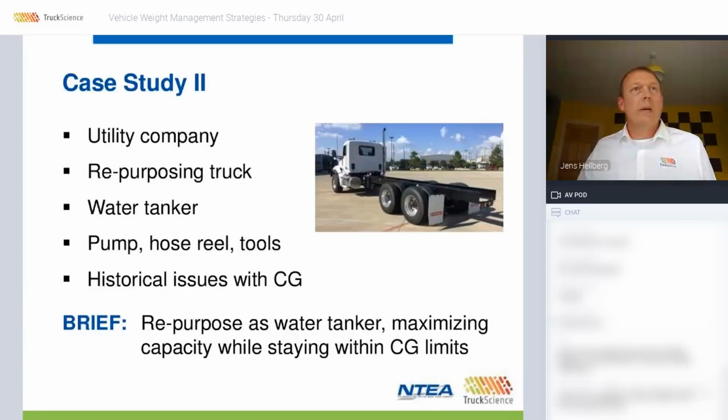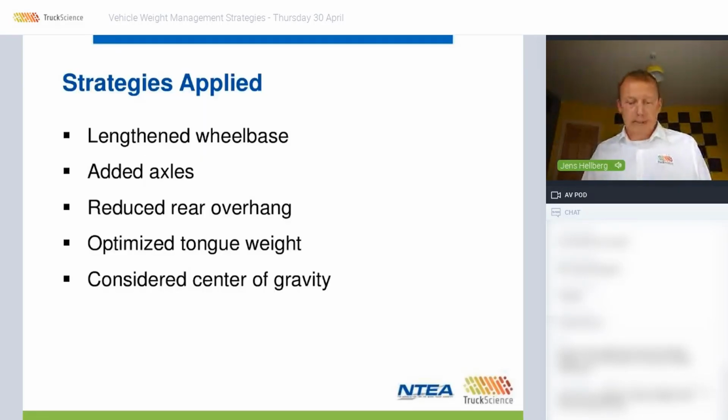Thanks. Right, so if I go back to my PowerPoint here. What have we learned? We've learned that allowed weights across consecutive axles increase with the number of axles and the spacing between them. As we saw in the two case studies, these two strategies probably made the most amount of difference. Adding a pusher axle increased the payload by a few thousand pounds in each case.